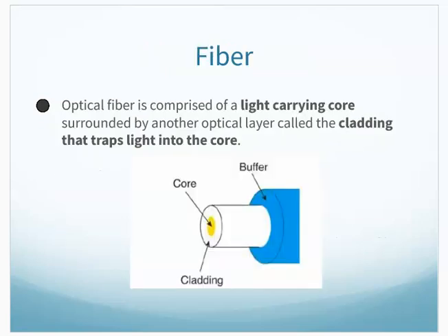The fiber itself is made up of a couple basic parts, the core and the cladding. The core and the cladding is all glass, so when I'm looking at the actual glass stub, I'm seeing the cladding, but inside is the core of the fiber. That is where the light is actually traveling. Around the outside of the fiber is typically buffer. Not every fiber optic cable is like that, but a lot of the ones we would deal with in premise cabling would have a buffer around the outside, which almost kind of reminds you of insulation.